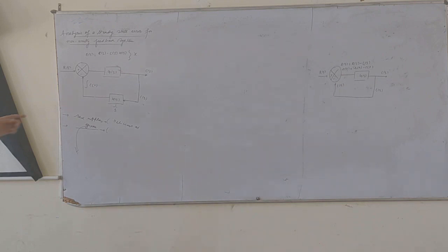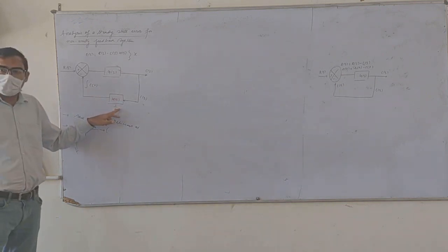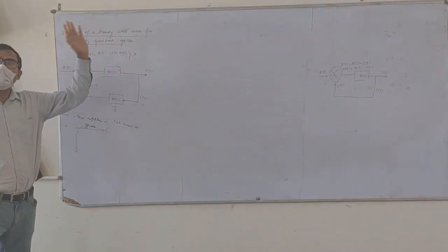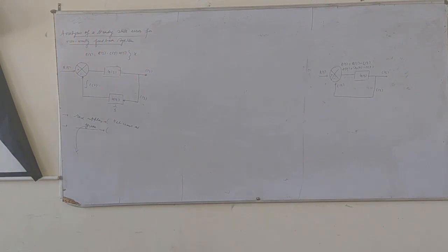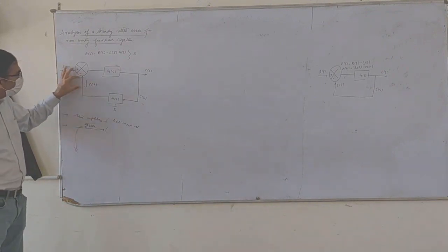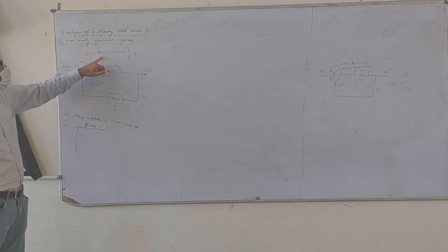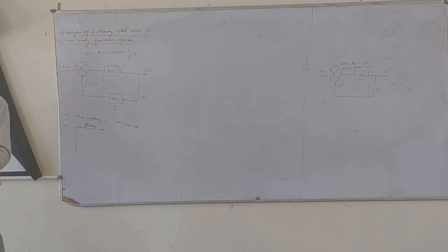We are taking an output here, let's say an integrator, so we are taking the integration of the output. We are not taking the exact output. Then when we reach here, that's an integrated output. We are finding an error between an input and the integrated output, which we do not have to find, because the error definition is that we have to find an error between an input and exclusively the output. So this is a bigger mistake. But most of the books are doing it.